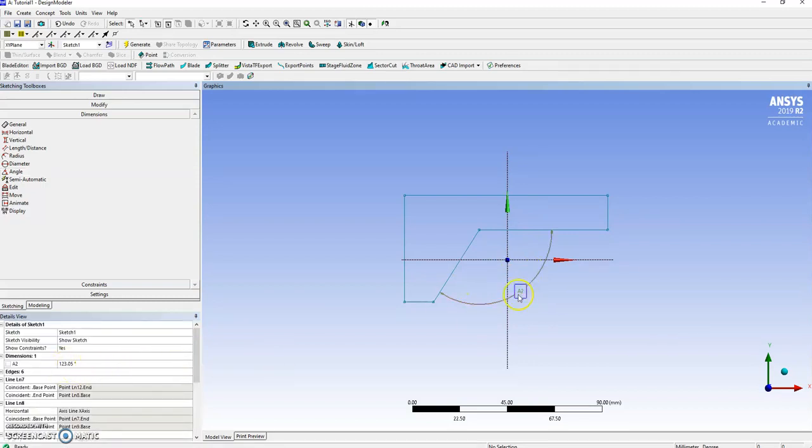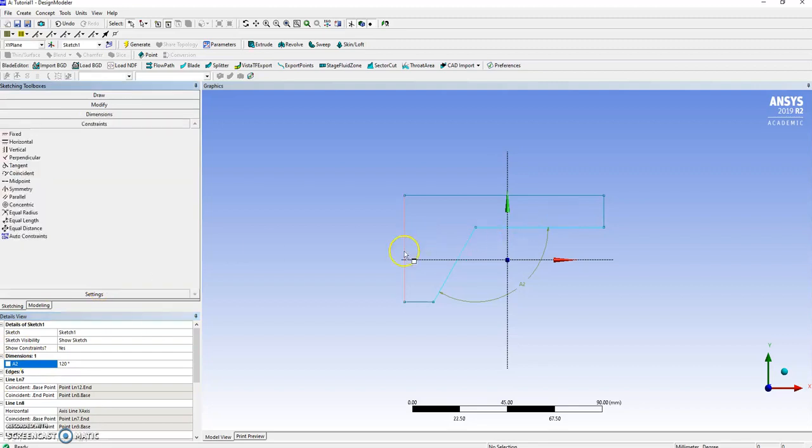I want to modify now, so it creates a value for a dimension, and you modify it in the sketch at 120. That's fixed. I'm going to put a constraint to force parallelism between these two lines. Let's force it.